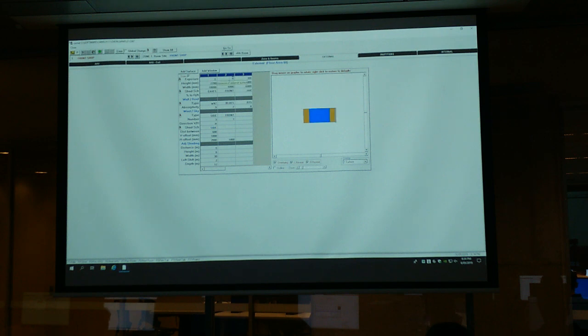If we have a look at the north wall, that's the wall material, and that's the shading, and that's the name of the window, and then offset, vertical, that's horizontal offset, the yellow area from the blue to the reveal, this side.